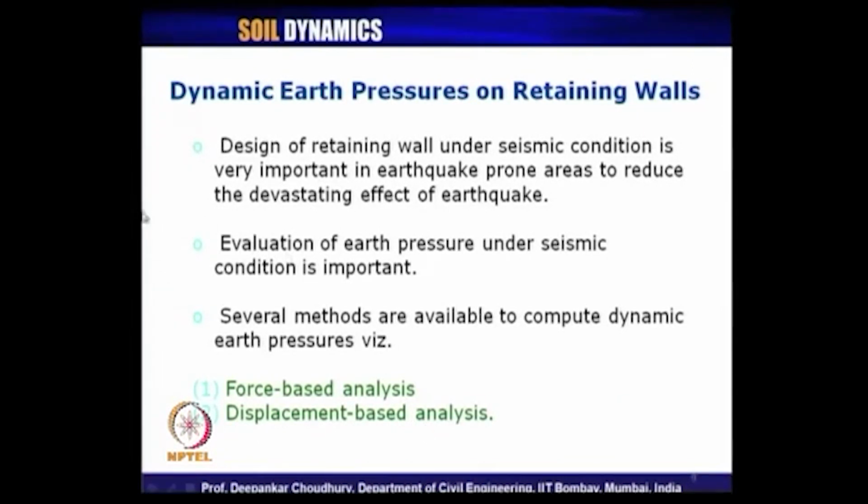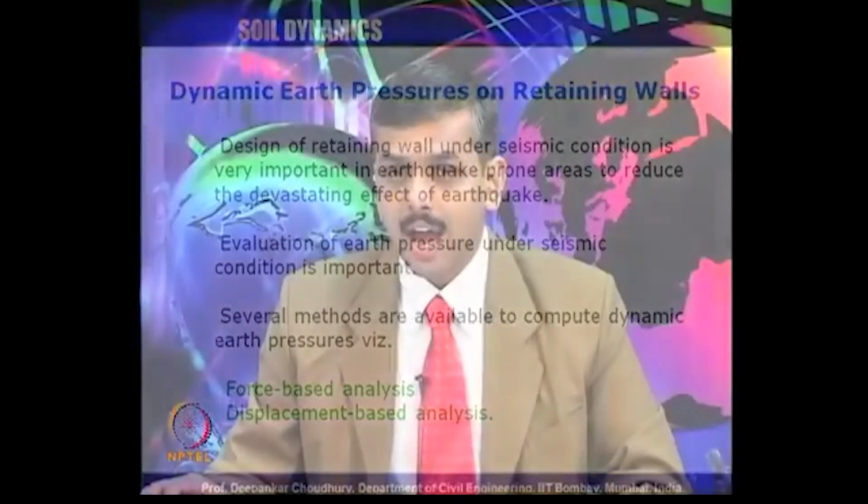As the name suggests, in the force based analysis, we are considering mostly the forces acting at limiting equilibrium conditions on the failure zone, on the wall, etc., to find out the earth pressure acting on the wall, whether it is passive earth pressure, active earth pressure or earth pressure at rest. For different cases, we can get them through the force based analysis.